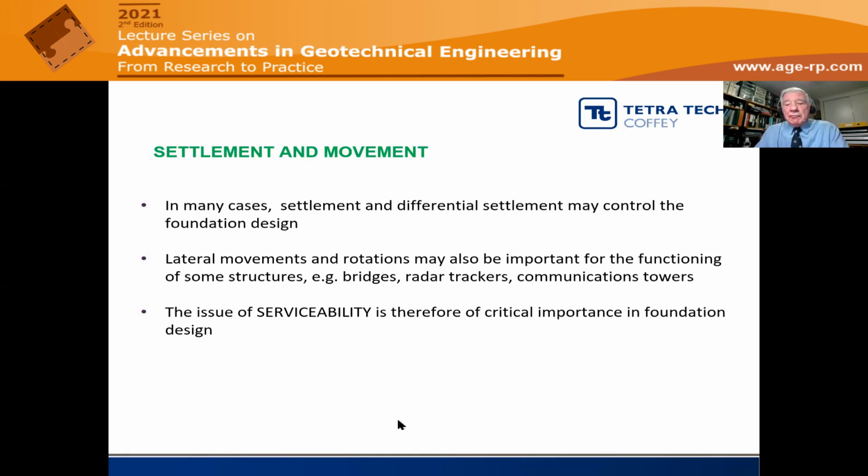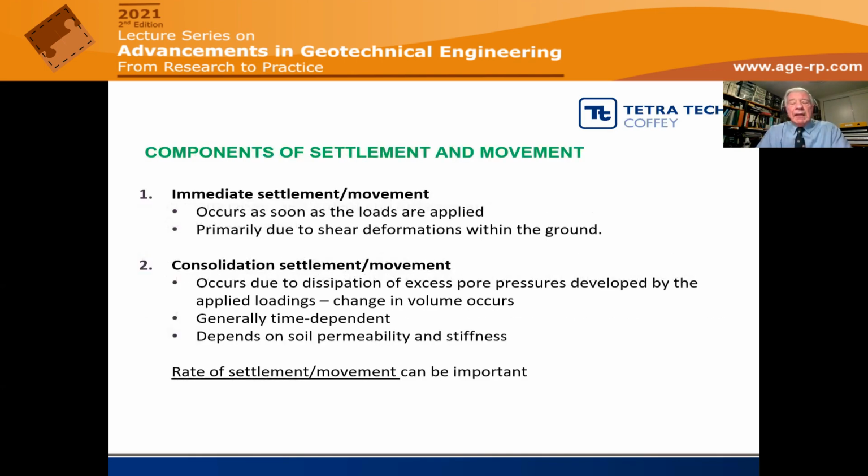So serviceability is of critical importance, and it's been increasingly recognized as such. Once upon a time, you just did a factor of safety 3 calculation, and that was your foundation design. Now we have to be much more specific about serviceability.